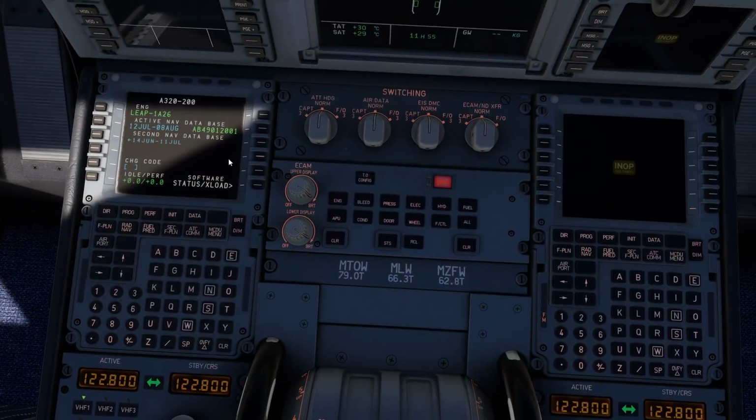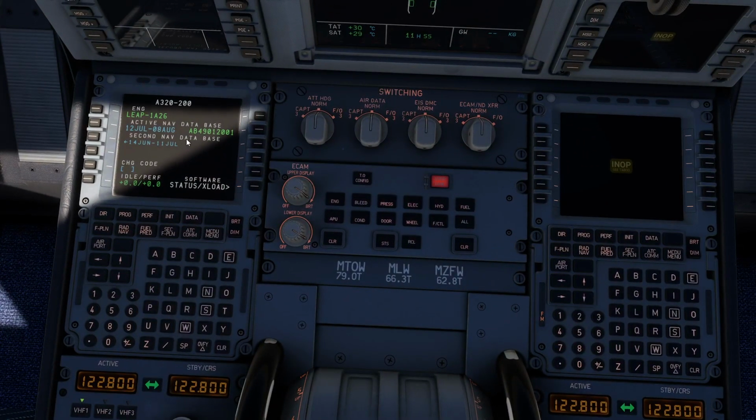So we go back to the MCDU. This is linked obviously with your Simbrief now because you input your pilot ID. Go to the init reference page and you'll see here the init request. Click on that and it will load up, as you can see from your Simbrief, everything that needs to be loaded. All you need to do is put your cost index in. So today the cost index is 21 for me.